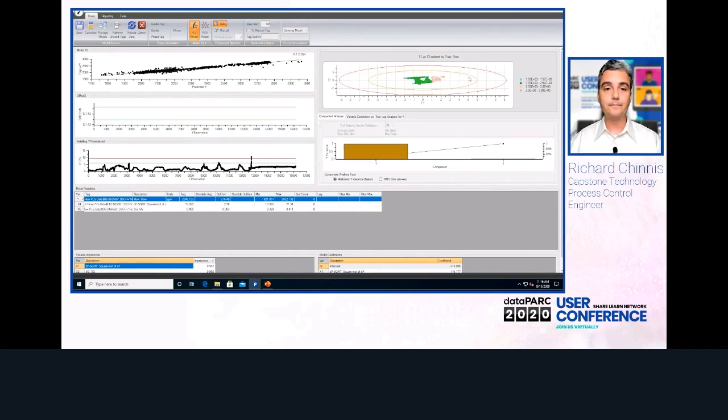It's packed inside our concentric circles, which again graphically says that all of the data is fitting the model well. This is a common Y to Y plot. You can see this is the original Y, so this is the values that we had coming from our trend. And this is now the predicted Y. They're plotted against each other. They're very close to that line. And you see our R squared is ridiculously high, which you would expect it to be when you're using flow as a model based off of the square root of dp. So you'd think with that kind of R squared, we're done.